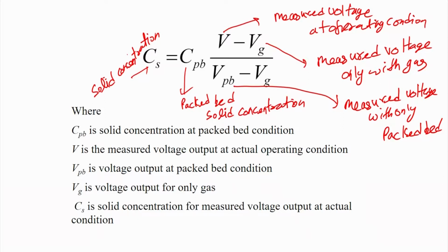So, you do the calibration at two different conditions and measure the voltage recorded, because the capacitance change will be recorded in terms of voltage. What will be the voltage recorded if only gas is flowing between the plates, or flowing with the needle touching that gas? What will be the voltage recorded once you insert the probe in a packed bed?